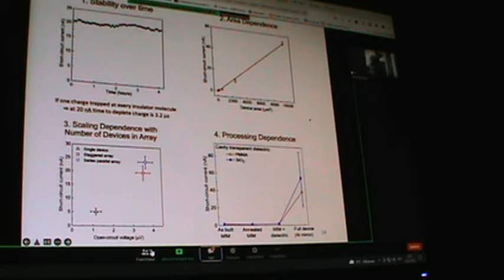Might it just be due to something in our processing, because we're cooking the devices as we build them? So we made measurements first with the basic metal insulator metal device. There was no current. We heated it to the temperatures that we would use for processing, no current. We added the dielectric, the transparent layer that we have, and for making the Casimir current cavity, again no current. Only when we put the mirror on do we all of a sudden see a current.